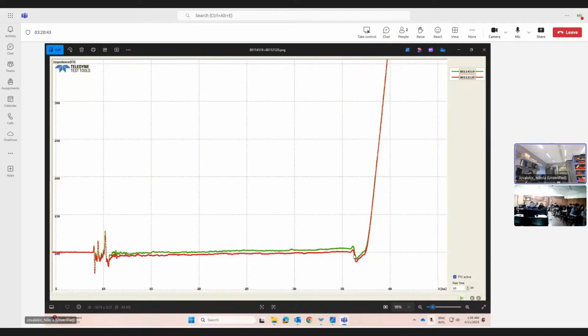And we come here to this point. You see a drop in the impedance, but this is a very short track, and then it goes very high. It means that actually the signal encounters the open side, which is to be expected. So this is how the impedance profile looks like.